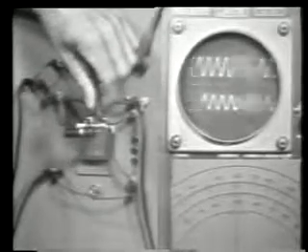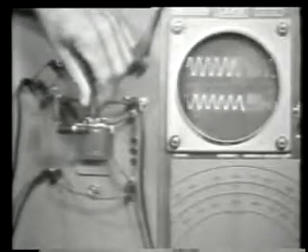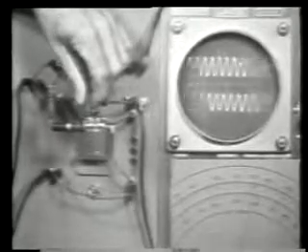Using this inductor and this capacitor, and with the addition of this resistor to the circuit, let's design a filter circuit that will pass a band of frequencies between, say, about 500 hertz and 700 hertz, with a center frequency of 600 hertz. Now, we're only going to be passing this small band of frequencies. The rest of the frequencies we want to reject.